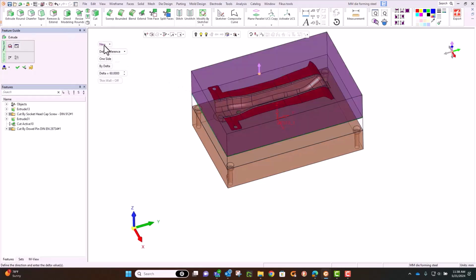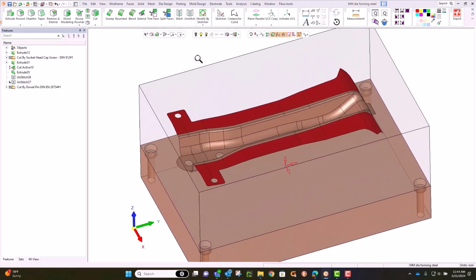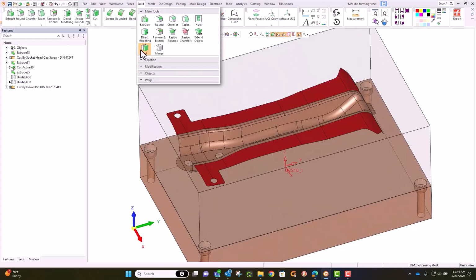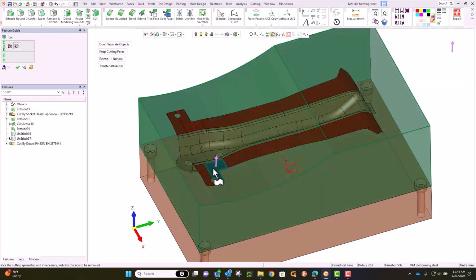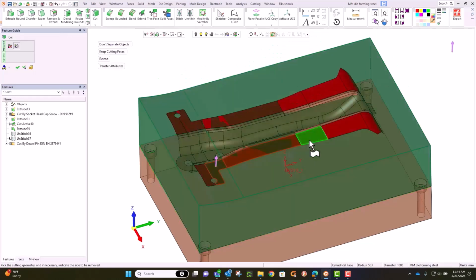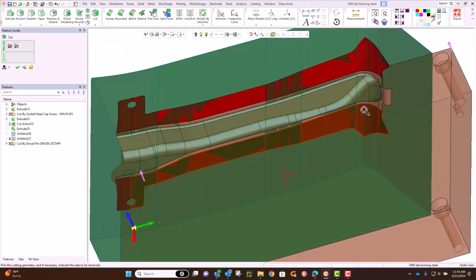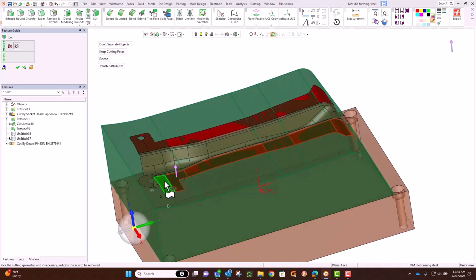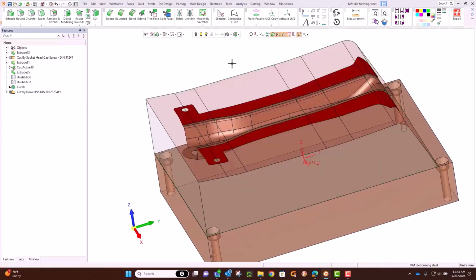Here we're working again with solids, parametrics, but we have a hybrid environment that allows us to work as a full object volume or as an individual sheet. So just going through patiently, picking each one of these flange surfaces, and you can see how it's changing the shape of that die steel. All right, so maybe I've got one more to pick out here. There we go. And I'm just going to cut it back to the flange. Simple as that. So this is an open solid, a sheet solid. It doesn't have to be perfectly airtight. You know, there could even be situations where there might be a gap or two.